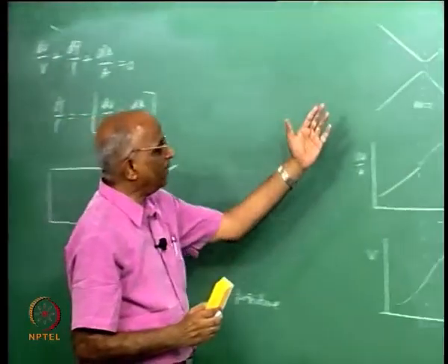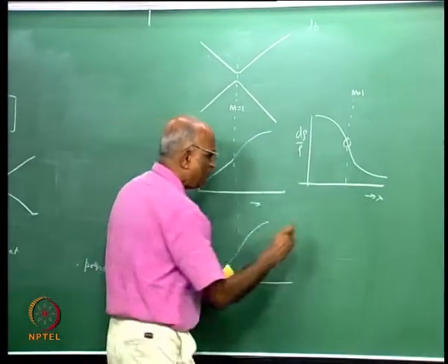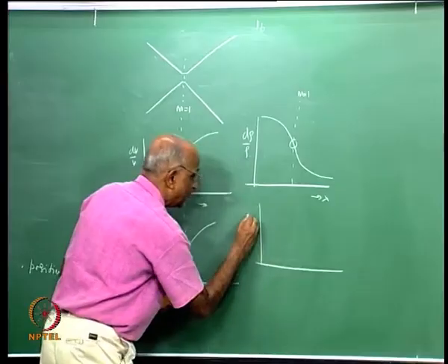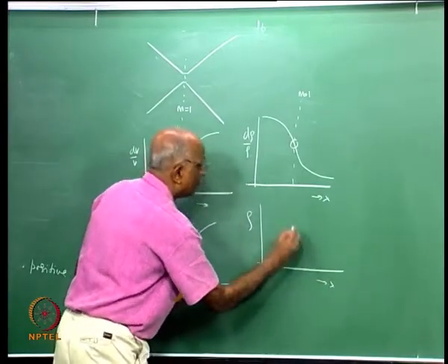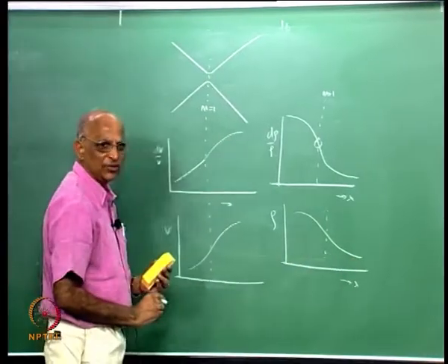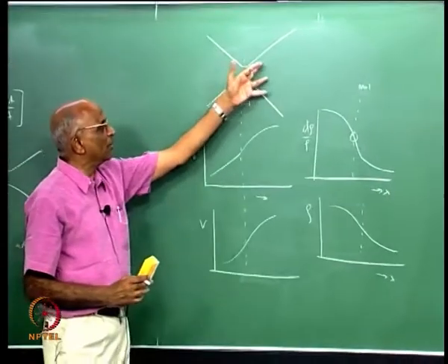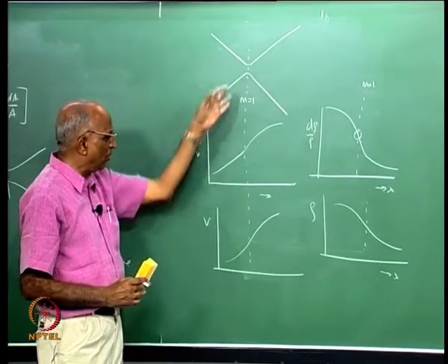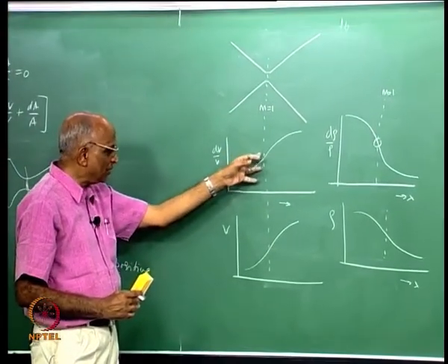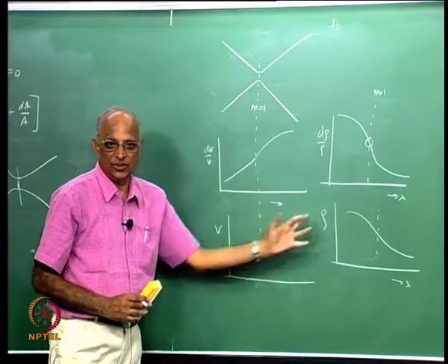That means at the throat portion you have a large change, and if I now plot my density as a function of x, with the throat over here, the density keeps decreasing. Therefore, for a convergent divergent nozzle for which M is equal to 1 at the throat, velocity increases, and density decreases.